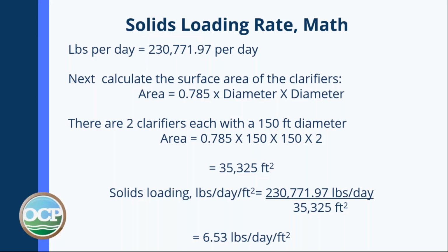So the area is 0.785 times 150 times 150 times 2, because there are 2 clarifiers, which gives you 35,325 square feet.